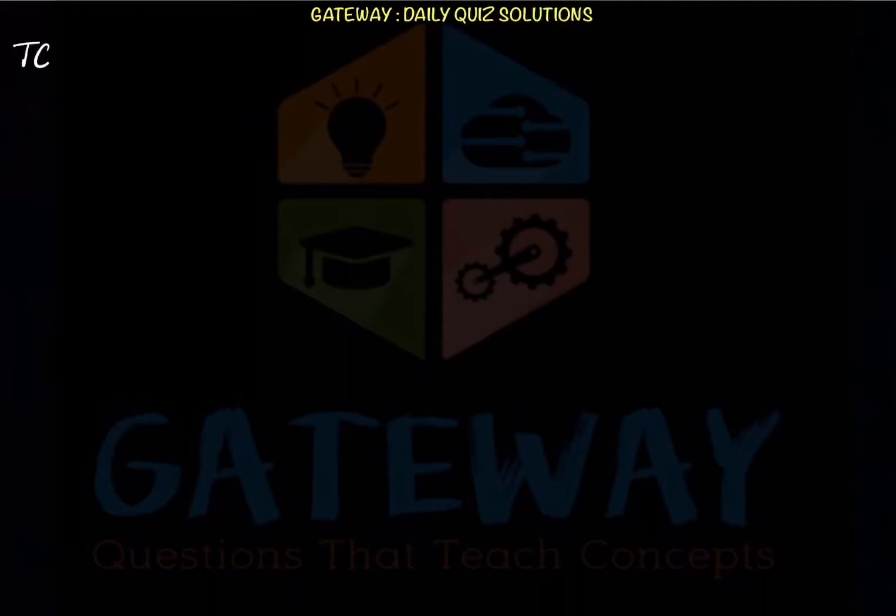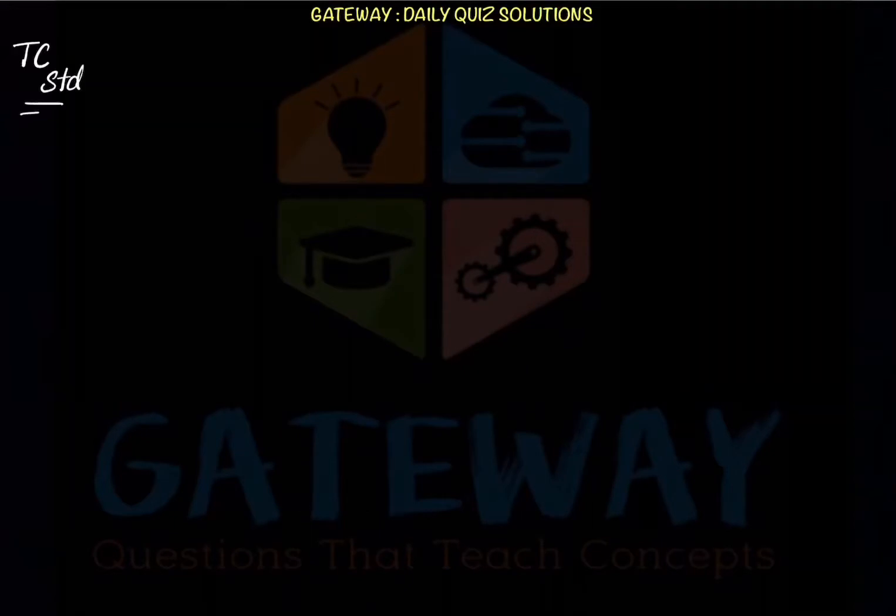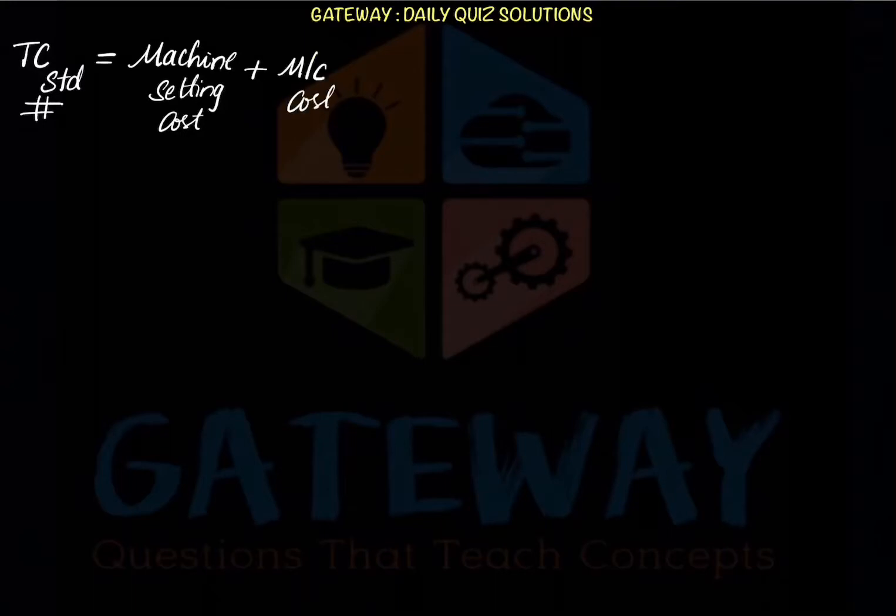So we'll calculate the total cost on the standard machine tool. How will you calculate it? The total cost involves two types of costs in this type of machine tool: machine setting cost plus machining cost. Both are different. Machine setting means the setting time we need. Here it was given that we need 30 minutes to set the machine. 30 minutes means 30 by 60, half an hour, and for that half an hour we need to pay the operator at the rate of 200 per hour, so we need to pay 200 rupees.